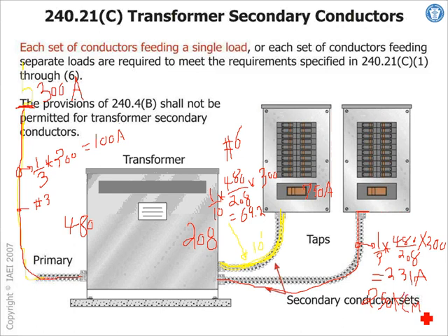All the way to the connection point. All the way to the terminals. So your conduit actually is shorter than that. Your conduits will be shorter than it, yeah, because you're measuring to the termination. The conductors, what you're tapping, is not the conduits.